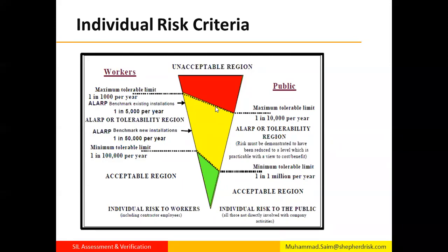Either the equipment is certified and tested, and through FMEDA we get the various failure rates. Those are tested failure rates. Or we get the failure rates from user feedback, that is, from industry feedback, and we have a good database in Sintef, Exida, or other databases, and we can use both.